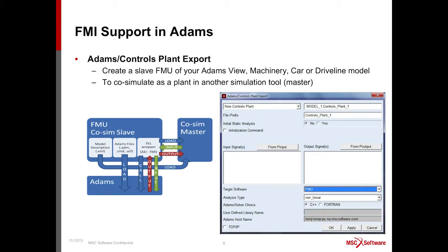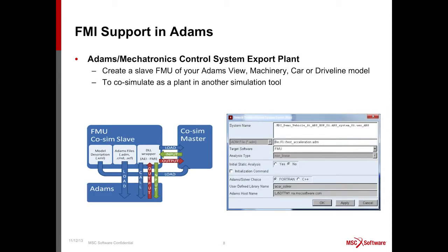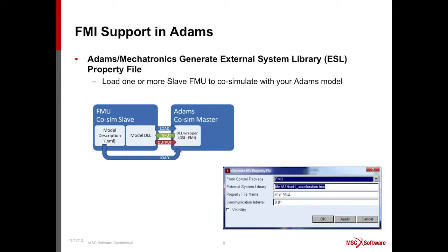So whether it's exporting or importing, and then also Adams mechatronics, which provides a much richer layer, including signal manager for your inputs and outputs, and units, better units control, delay functions, all that good stuff on top of the Adams controls layer. Again, for Adams mechatronics, we both support the export of your FMU as a plant, or import and generate an external system library within the Adams Car database.